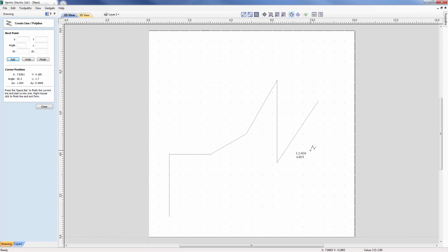And that will create a point that's incrementally 2 in X and 3 in Y. Now, finally, if I wanted to create a point at a defined absolute position, I can come into the entries and type in 5x 5y, and that will have created my next point at an absolute position of 5 5, and as you can see, that is the center of our job space, which happens to be 5 5. So those are all the different options for creating a polyline, and you can see all those options within the help menu.